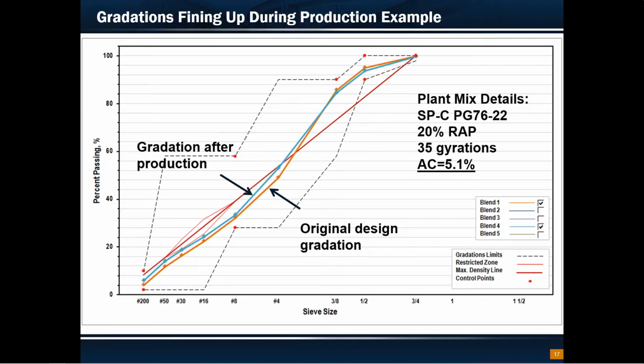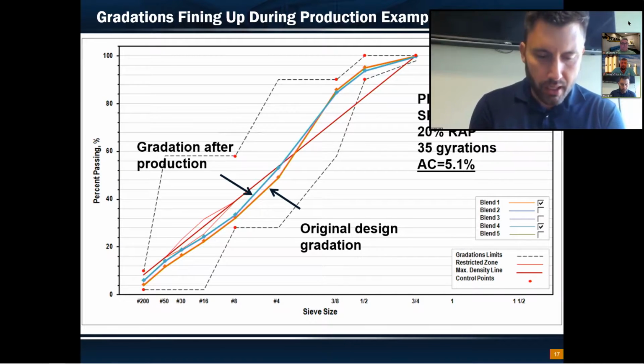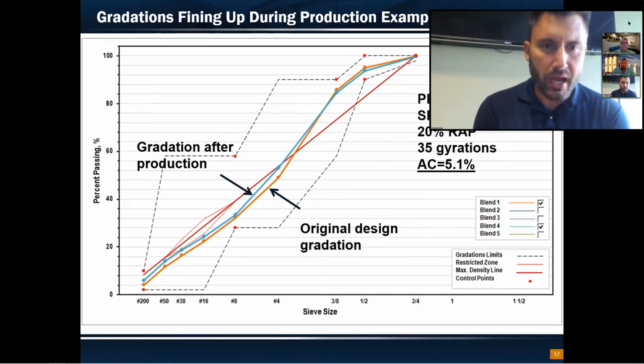All right, here's a question for you, Ryan. Now that we are several months into the 3077 spec, what is an average increase in the asphalt content percentage across C and D mixes versus where they were with 3044? So, Jim, I would say somewhere right around 0.5%.